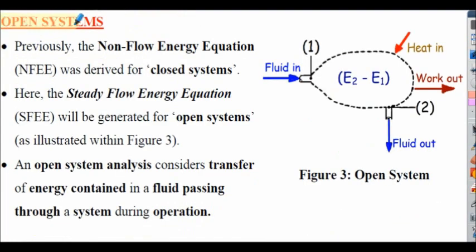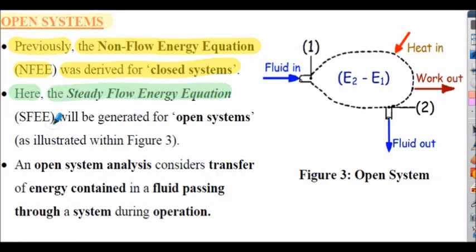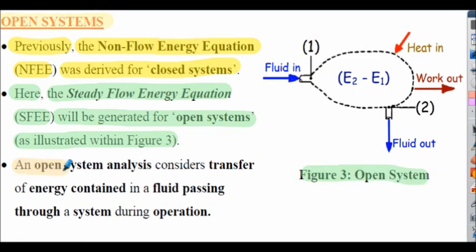Let's consider energy in open systems. So in our previous presentation, the non-flow energy equation was derived for closed systems. In this presentation, the steady flow energy equation, acronym SFEE for short, will be generated for open systems, as illustrated in figure 3. An open system analysis considers transfer of energy contained in the fluid passing through the system during its operation.